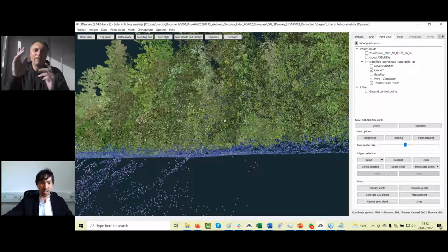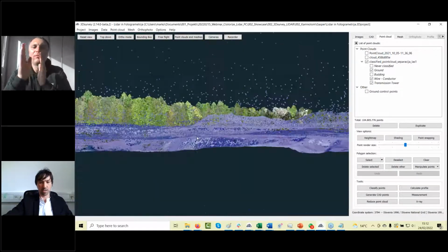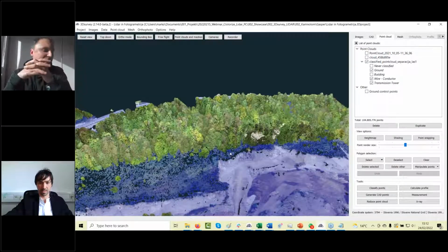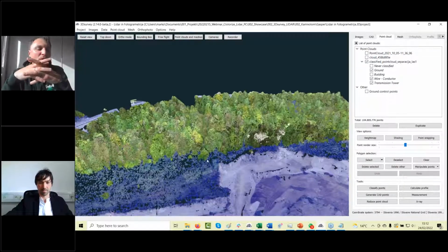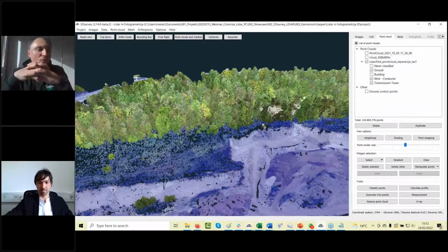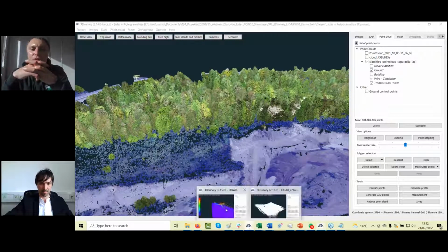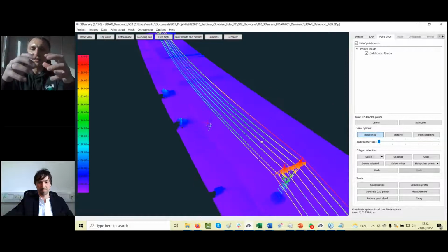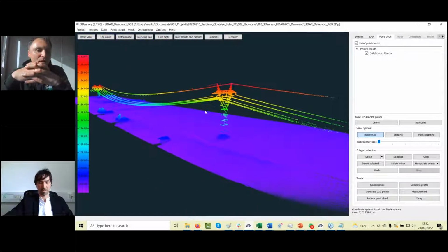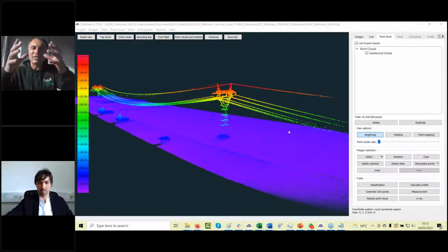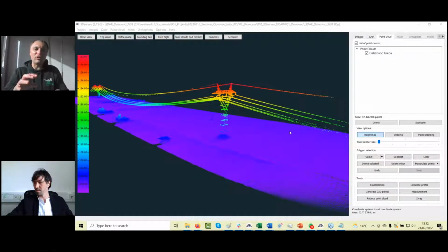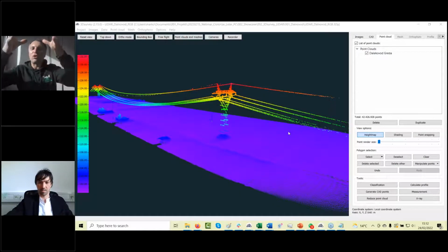And with this data, I just want to add, Marco, can I add a sentence? When we made a survey of power lines, we tested several solutions, solid state LiDARs and Velodyne LiDARs, especially HDL LiDARs. After that, when we combined different point clouds on the same power pole, we saw that, for example, HDL just saves the points of the real position of the power pole.